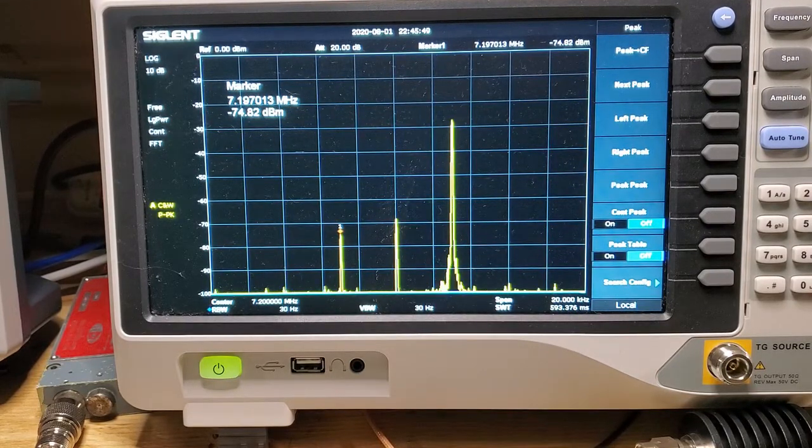So let me just go back again. I'll swap the coefficients on the left and the right side again, recompile and flash the code, and you should see that go back to the lower sideband there. And there we go. So I guess that's the completion of part 2. I had a lot of fun doing this. This is exactly what I wanted to achieve here, which is doing some nuts and bolts DSP and ending up with that 0 and 90 degrees Hilbert audio filter.